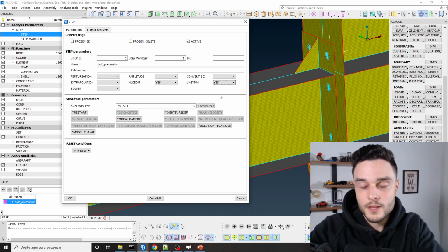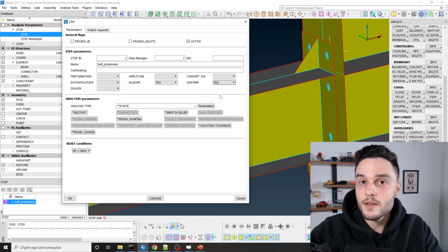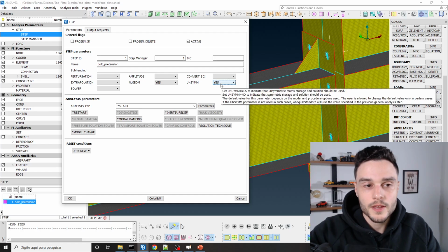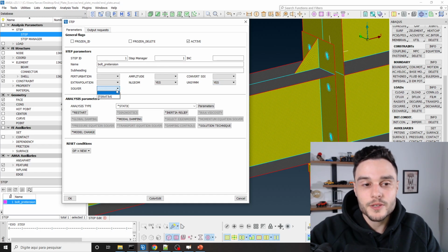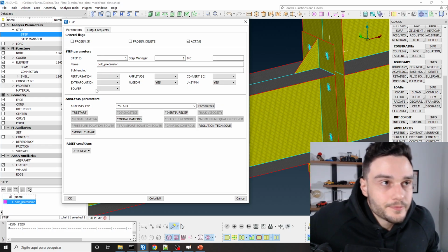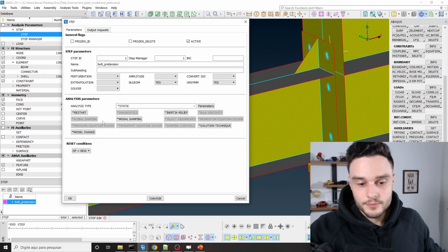Okay, a non-linear contact is one that allows separation. So we can have separation in the middle of the analysis, and then we can have contact again, and this brings a nonlinearity. All right, now we understood this. Now we have this option here, solver. Let's remember that, let me show this.